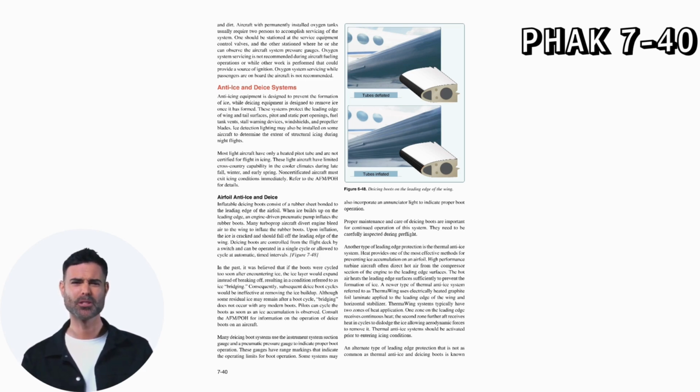Many de-icing boot systems use the instrument system suction gauge and a pneumatic pressure gauge to indicate proper boot operation. These gauges have range markings that indicate the operating limits for boot operation. Some systems may also incorporate an annunciator light to indicate proper boot operation. Proper maintenance and care of de-icing boots are important for continued operation of this system. They need to be carefully inspected during pre-flight.